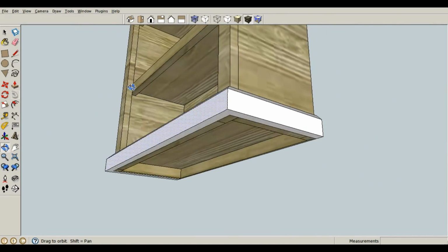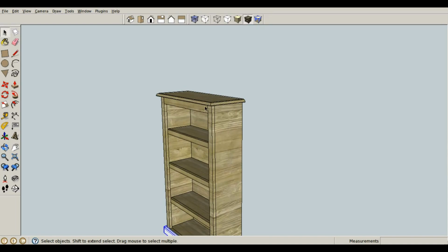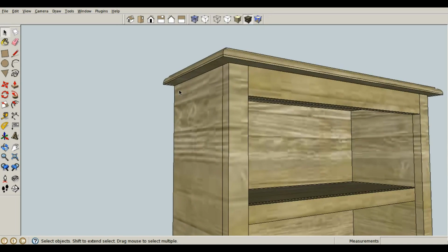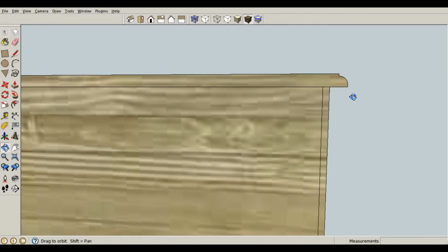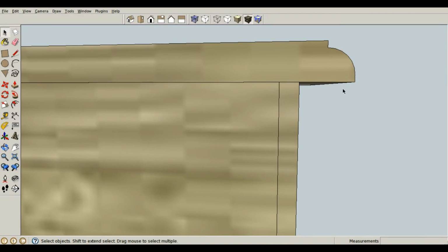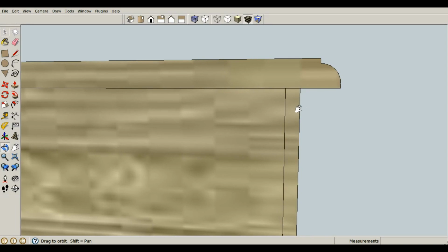Very quick, very cool. So let's do the same thing up here at the top. Let's add a little bit of molding to this top piece, and I'm actually going to go on the back side to draw. It's a little bit handy that way sometimes. Just for the sake of it, let's go Alpha line from here. Let's go out 0.75 inches, enter. Let's go down 0.25 inches, enter. Down again 0.5 inches, enter. And you'll see why in just a second.